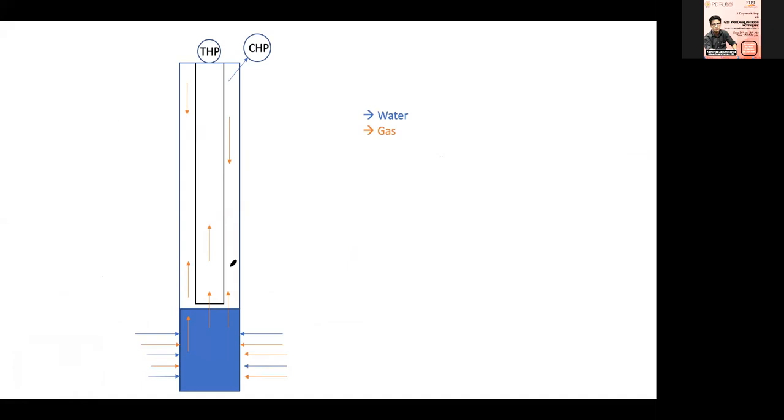When you close the well, suppose you have liquid loading there. You are going to have a back pressure in this direction. So this back pressure will push the liquid back to the reservoir, and also some gas will come out of the reservoir. This will charge your casing annulus, and your pressure will increase in the casing. You will also notice some increase in the tubing. And when you open this valve, the flow arm valve, there is a sudden pressure drop in the tubing. So basically you are opening it to atmospheric pressure.